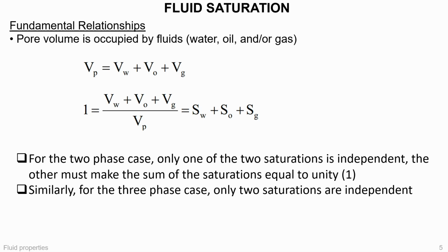In two-phase flow, only one saturation is independent. In three-phase flow, only two are independent. This is crucial in simulation and interpretation. When one fluid increases, another must decrease.